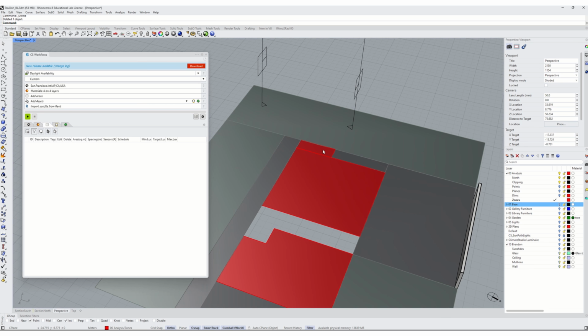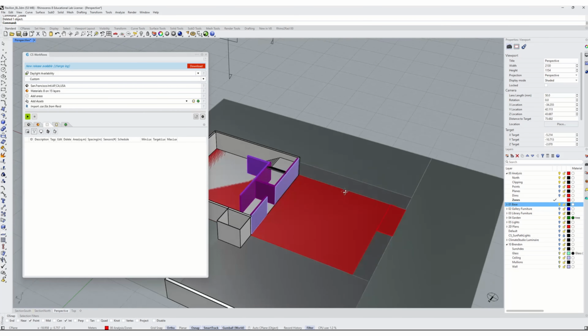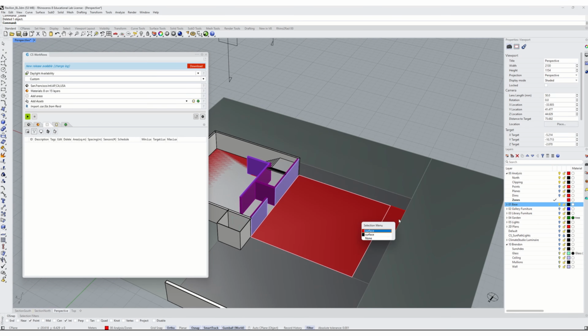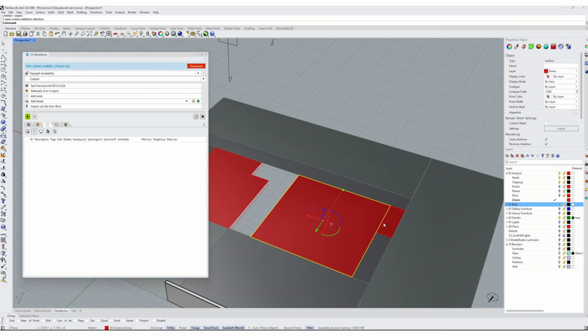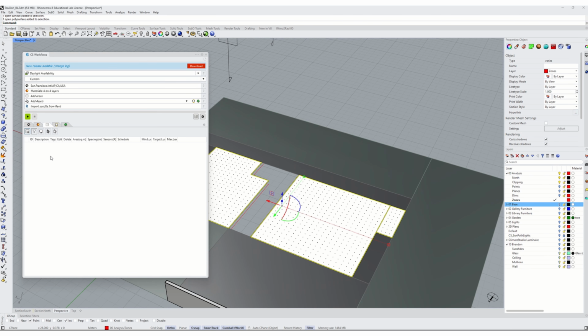And then for this one, just making sure that it's okay on this edge. I actually want these to be the same plane. I don't want two separate ones, so I am going to Boolean these together, Boolean two objects, and hit enter, and now it will be one object. So I can click on this and click on this and add those zones. I'm just going to press OK. We can edit this later.